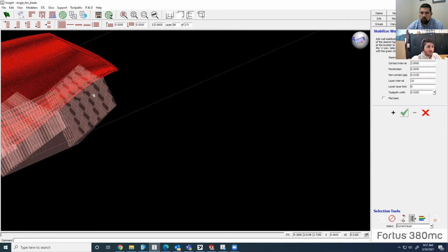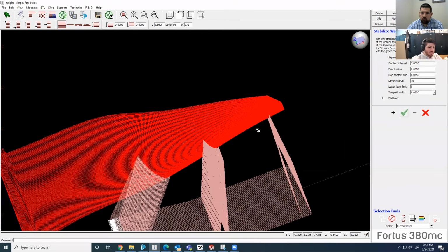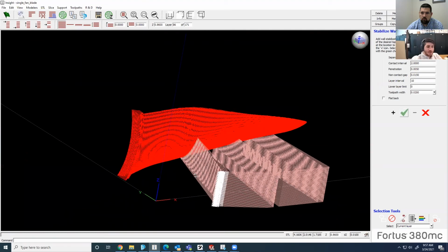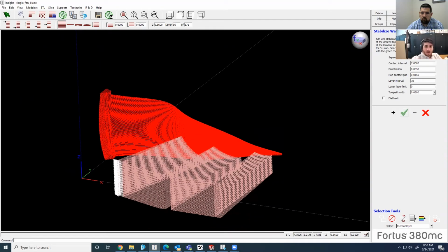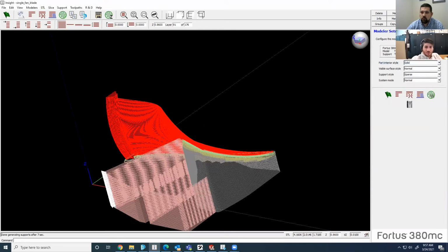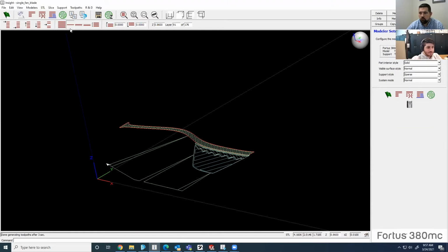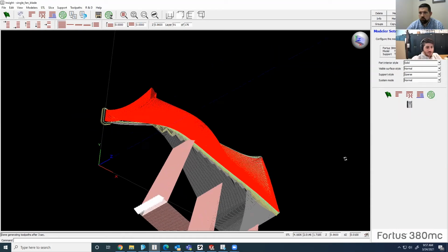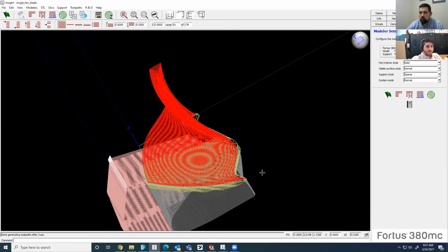let me try to orient this screen. It'll embed directly into the model. That'll keep it essentially bolted right down to the build plate and negate any movement of the part during building. So that will interface with the support material, interface with the part, and just add some secondary support to make sure that you get your part out as clean as possible. So as you can see, it will build through the support material here and interface with the part.